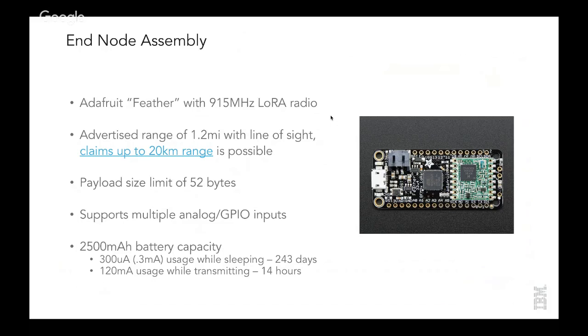There were two main choices I was seeing, at least in the message board. One was the Adafruit LoRa Feather, and the other was the Arduino Uno. I decided on the Feather mostly because it had a good range and a lot of support. I also liked that it had the option to go into deep sleep mode. That could drastically increase the battery lifespan, as the end node can simply wake up, collect some data, send it off, and go back to sleep for however long.